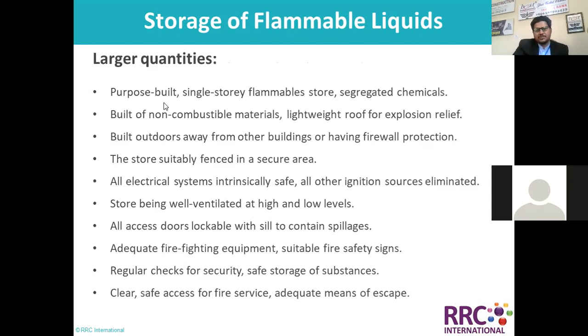For large quantities, use a purpose-built, single-story flammable store with segregated chemicals, built of non-combustible materials with a lightweight roof for explosion relief. So it starts with the design, and accordingly you will suitably fence in the source area, a secure area, with all electrical systems made intrinsically safe and all other ignition sources eliminated, and the store well ventilated. Again, it is the design and construction. During construction, you need to incorporate all the standards.